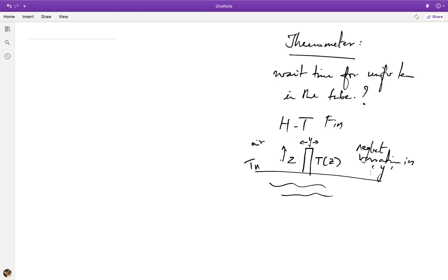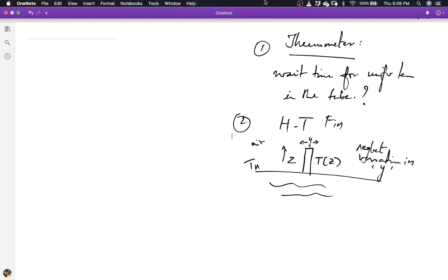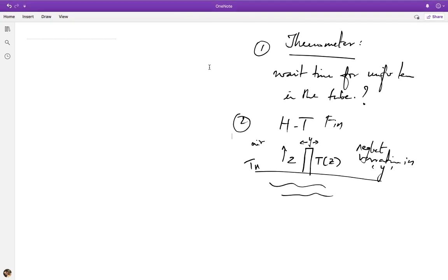But now again you can ask this question, how small is small, and what do we mean by instantaneous, and in comparison to what other time scale? So all of these issues can be addressed by scaling, which we will do in the following problem. Okay, but the point is now that these two scenarios that I have given you, this idea of a thermometer or the fin, these correspond to situations where you have a relatively thin slab across which you have diffusion of either heat or a scalar concentrations of a species. So let's first draw that before we proceed.